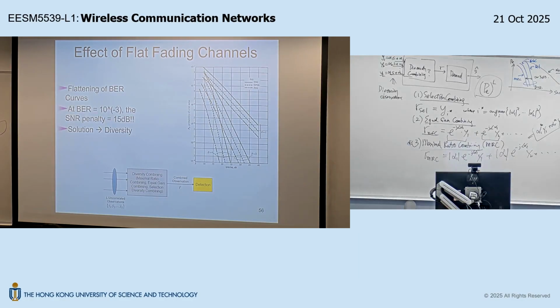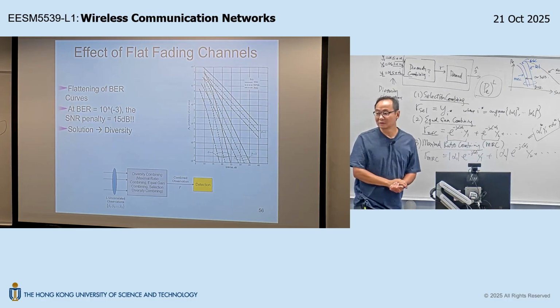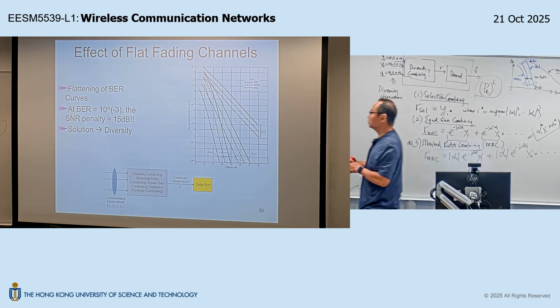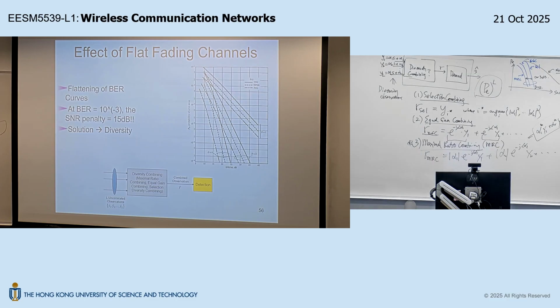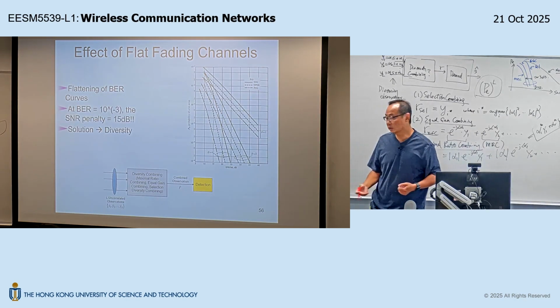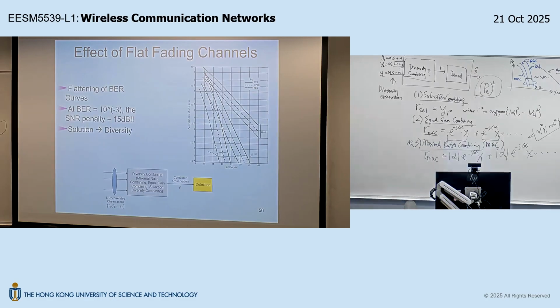If I have 8 receive antennas, I just partition this into 8 pieces, right? But can I keep on doing this? Remember, the channel estimation, let's say alpha i hat, is given by 1 over Ni times the summation, i from 1 to Ni, of Y_pi, right? Why do I need to take the average? I take the average to enhance the quality of the estimation, right?